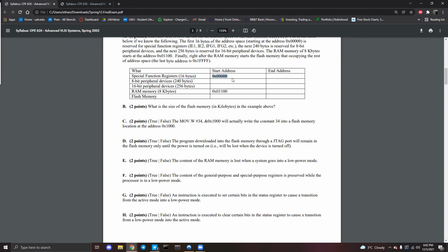The starting byte address is right here, so you can just move up. What you'll do is add 16 and subtract 1, because each address is a byte address. As Sydney said, you add 16 and subtract 1. So what does that realistically mean? Well, in hexadecimal, you can represent 16 distinct values, from 0 to 15. Therefore, 16 minus 1 is 15, and F is 15. So your end address here is 0x0000F. That is all, there you go. If it were word addressable, it would be E.